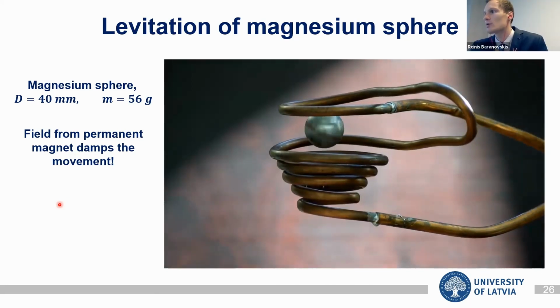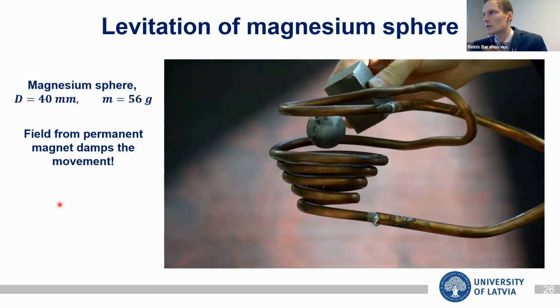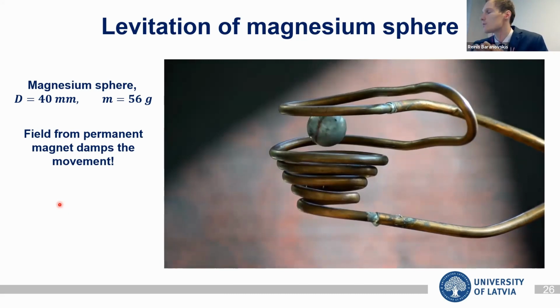In this particular electromagnetic levitation with induced currents, there is little use of it. Another way to explain it: these induced currents are harmonic in the workpiece, and the same goes for the magnetic field. To get a static component, you have to multiply a harmonic part by a harmonic part.